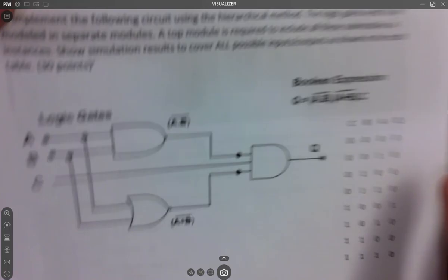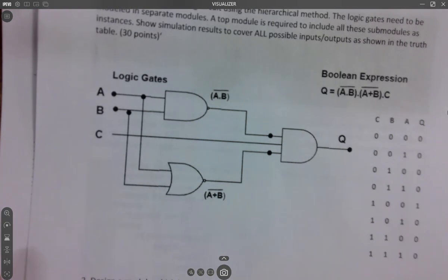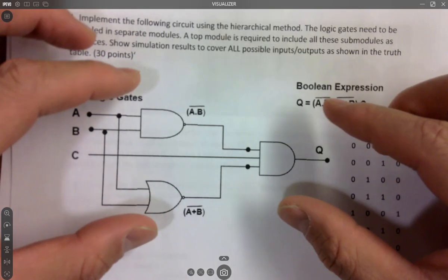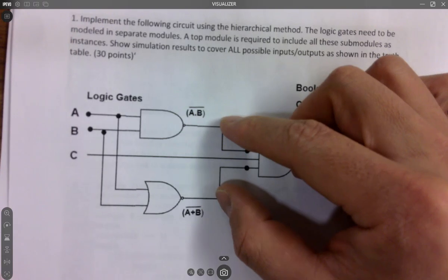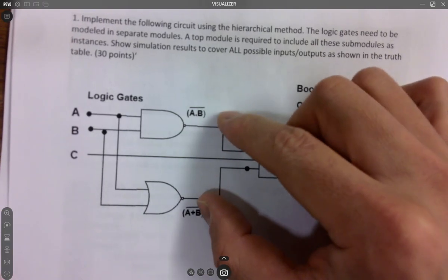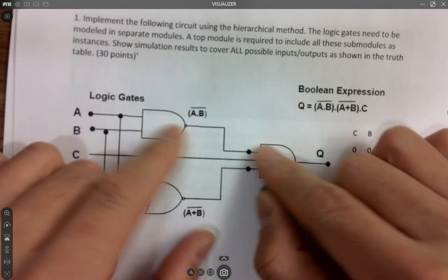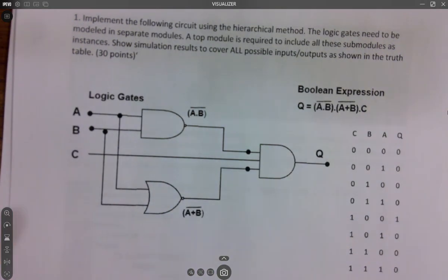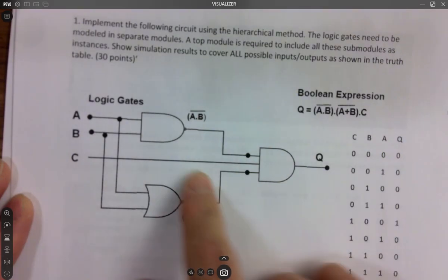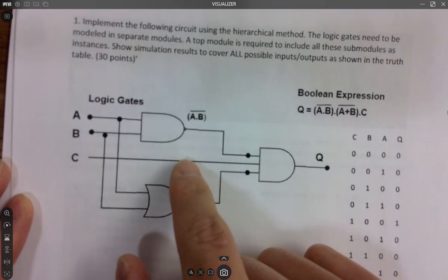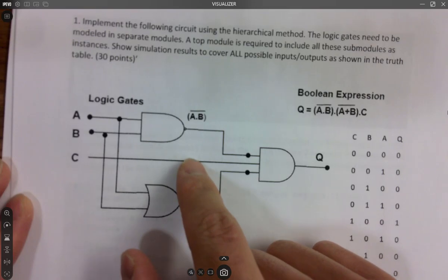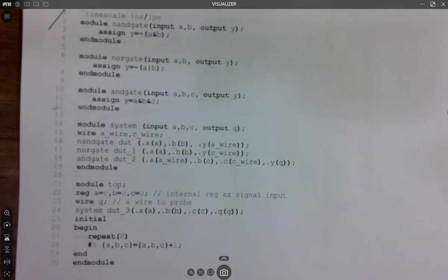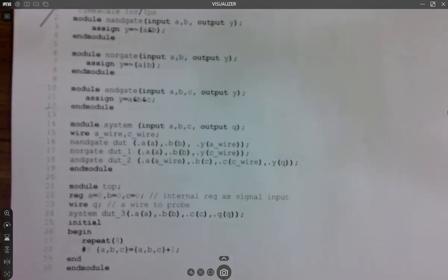Remember, we have done this many times, right? When you are putting all the sub-modules into a top module, if they're not directly interfacing with the ports, you just have to create an intermediate wire in the middle, like a floating wire, so you can indirectly short the two ports to the single wire and make the connection in your top. But now, since we have 1, 2, and this one is just a port, we don't need an individual wire in the top. If you look at the code here, it's hard to see, that's why I printed it out for you.